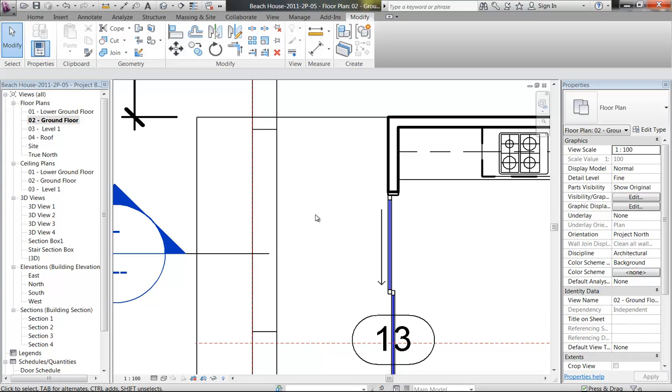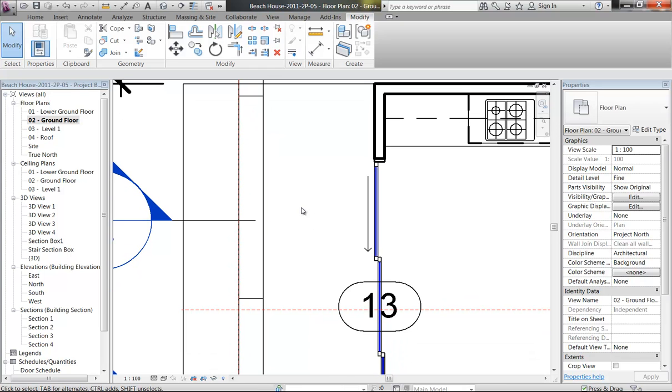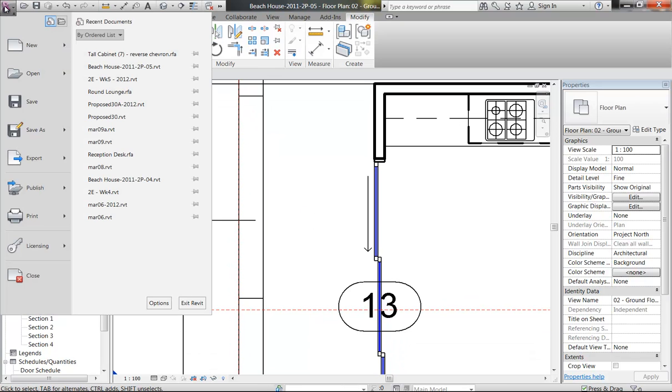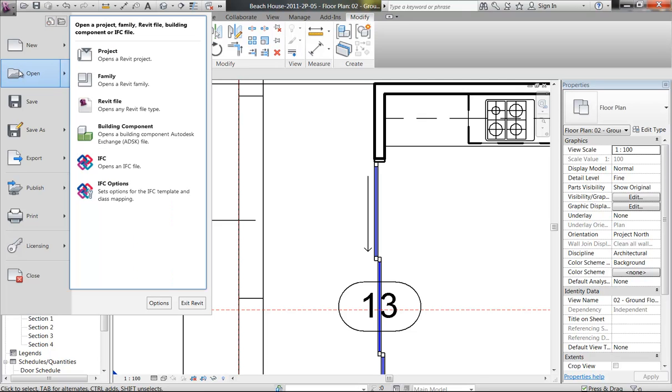or in Revit you'd call it a railing. Yeah, I think I put it in with the brief. So in the first year briefs folder, in the beach house folder, I call it beach house balustrade. Okay, so this is the thing you need to remember. When you want something that's a system family, you don't load it, you open the file.